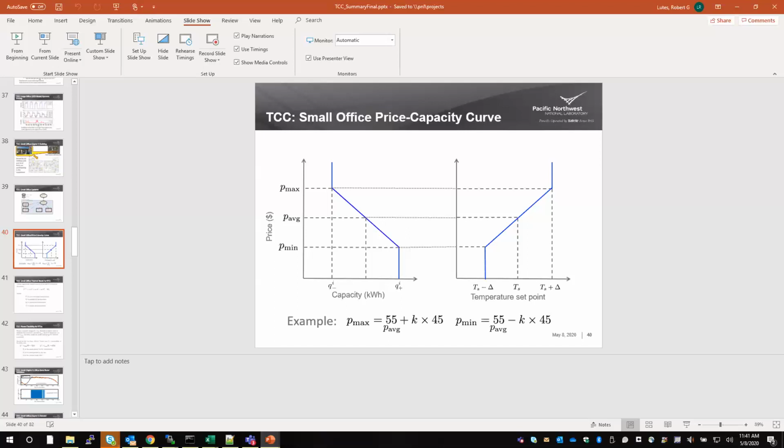Quick question. Sure. Have you had any luck extending those models to the dual max VAVs? Good question. We are currently working on that, and I believe Sen has a methodology in mind. We need to do additional testing and validation that those actually work correctly, and then update our code to allow for the dual control for both heating and cooling simultaneously.